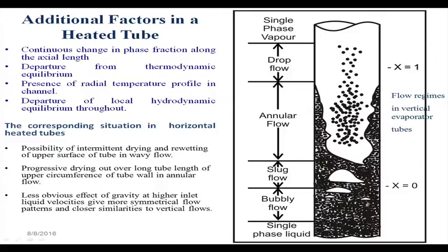So, therefore, we get something like the bubbly flow pattern. Now, again, as this heated liquid, or this two phase mixture, starts flowing up, we find that more and more bubbles are formed. As more and more bubbles are formed, they come very close and start coalescing. The moment they start coalescing, naturally the vapor bubbles will assume their stable shape, which is nothing but the axisymmetric bullet shaped sort of a thing, or the Taylor bubble sort of a thing.